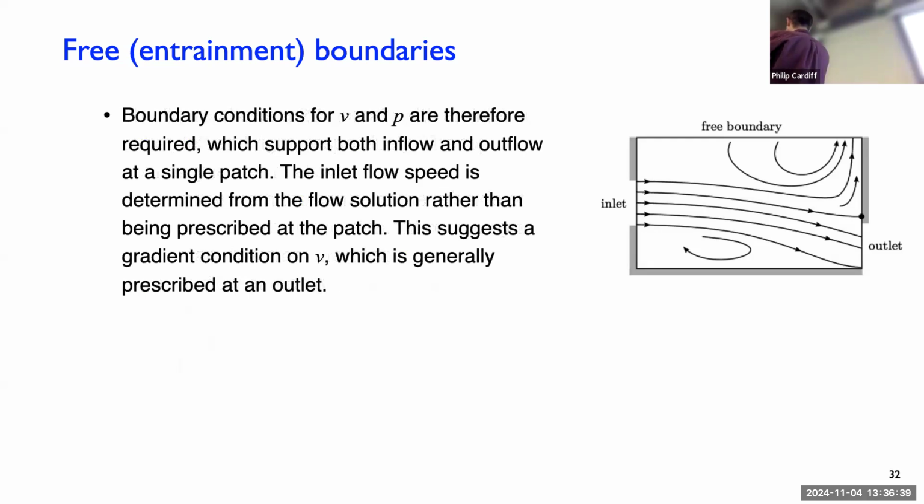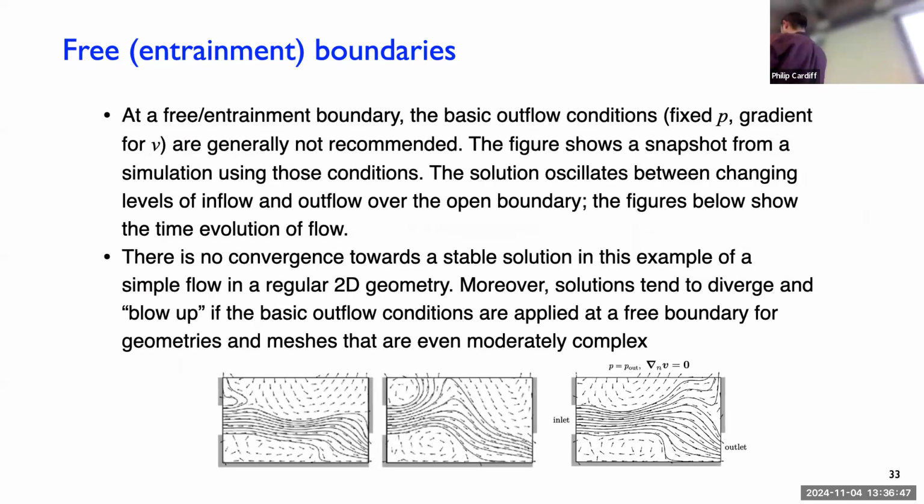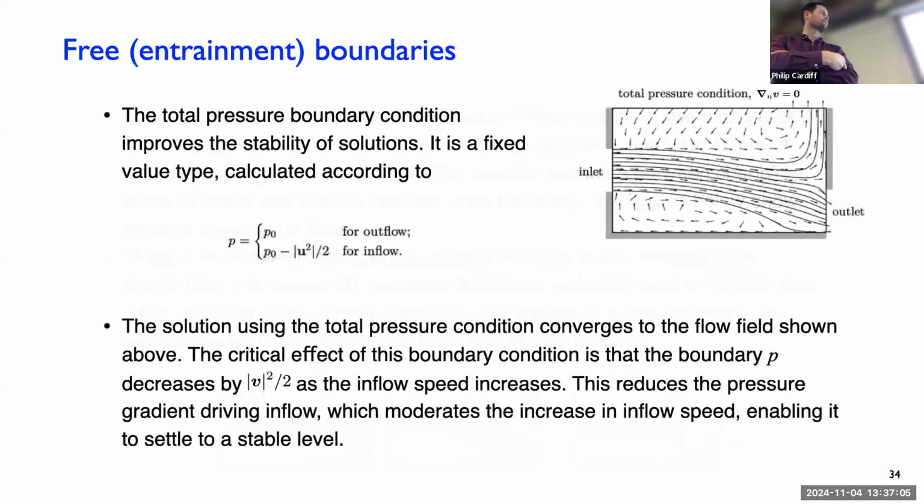So we need to specify boundary conditions for velocity and pressure. If we specify just an outlet condition on the top, the normal way to do that, and you set it up and run the simulation, it'll be unstable, it just won't converge. If you look at the intermediate unconverged velocity fields, they'll flip between lots of fluid going out and then fluid coming back in, in and out, and it's physically unstable. So if you set that all to an outlet, it won't be stable.